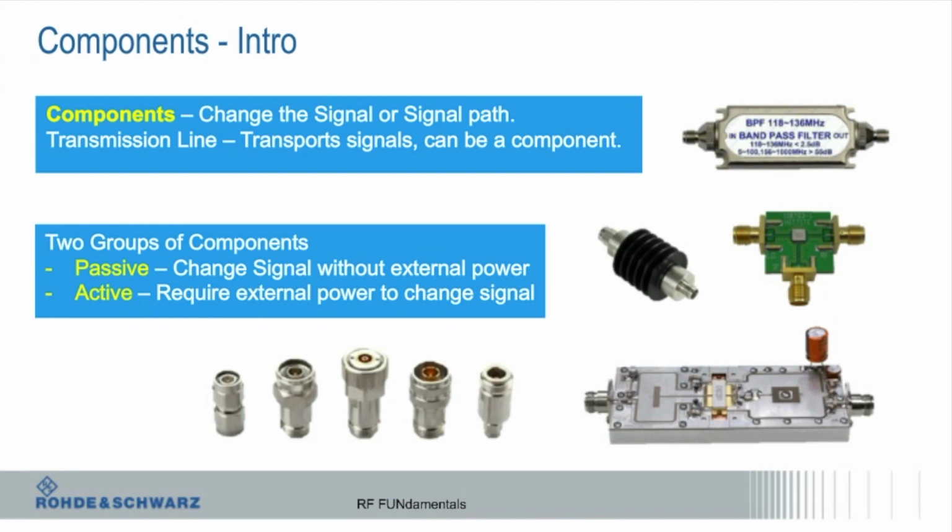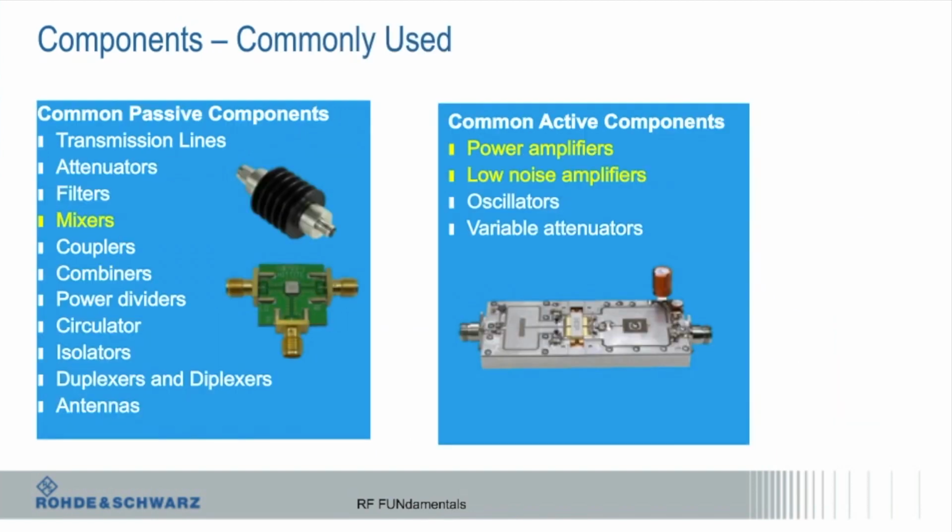But if you want to accurately measure what's the phase response, what is the input match, what's the output match, the reflection coefficient of my device, you really want nothing to make that measurement signal worse. So that's why you want to use really good connectors. But good point, thank you.